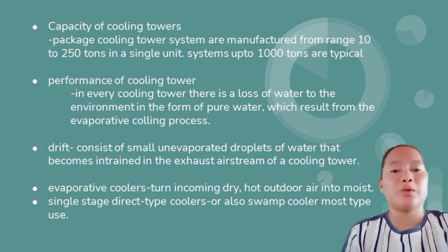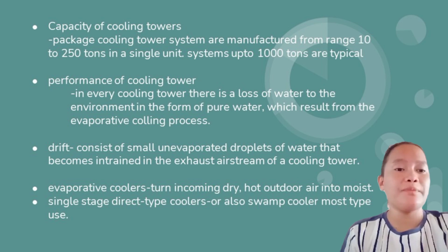Performance of cooling tower. In every cooling tower, there is a loss of water to the environment in the form of pure water, which results from the evaporative cooling process. Next is drift. It consists of small unevaporated droplets of water that become entrained in the exhaust airstream of a cooling tower.